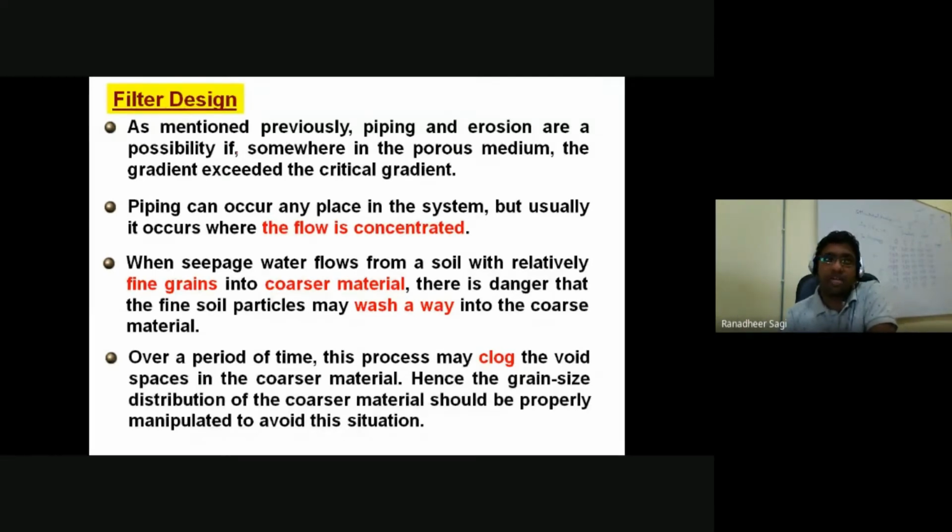In the case of piping or erosion, when the water is moving from upstream to downstream, there is a possibility of soil grains getting carried away with it. To prevent the soil grains from escaping from their position in the soil medium, we provide a proper drain, which we also call a filter.